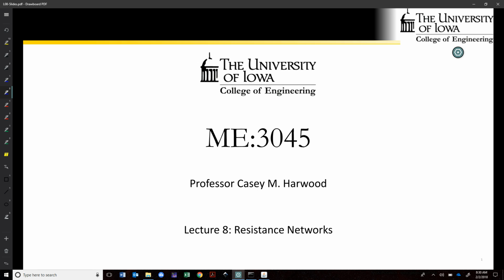Okay, so like I mentioned last time, today we're gonna spend like two or so slides just wrapping up the idea of one-dimensional conduction, kind of doing it the direct way, right? Which is set up your version of the heat equation in whatever coordinate system you're operating in, eliminate any terms you can, and integrate it to get your general solution, and then your constants of integration are defined by your boundary conditions.